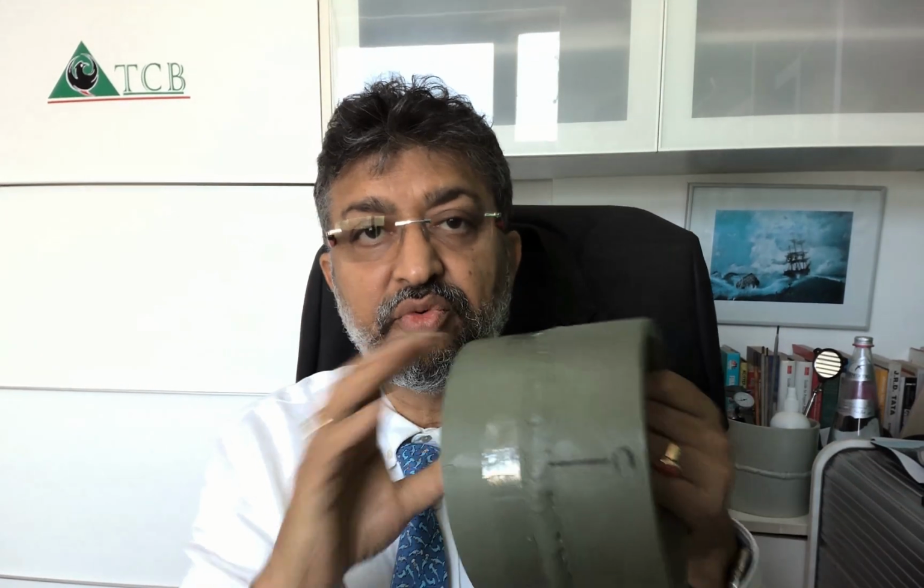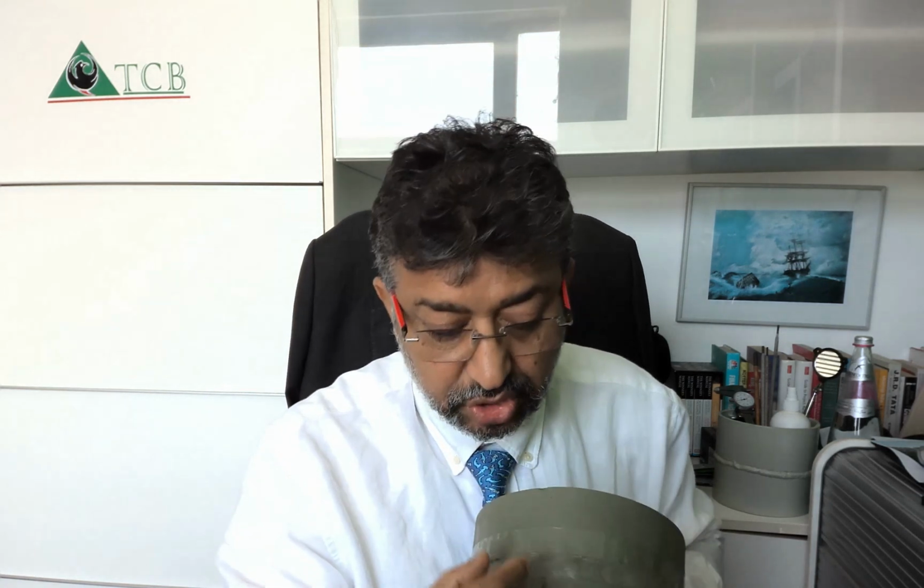Say this is the welded joint you have done, and this is how the cross section is going to look. So you are going to take the reduced section tensile test sample from here. The reduced section will be here, and the weld will be subjected to the test. If you reduce this, the failure is most likely going to happen in the welded joint. Even if it doesn't fail at the weld, if the failure happens in the plate or the pipe, which shows the weld is strong enough, this is also acceptable. But by reducing, you are making it possible for the weld to fail.